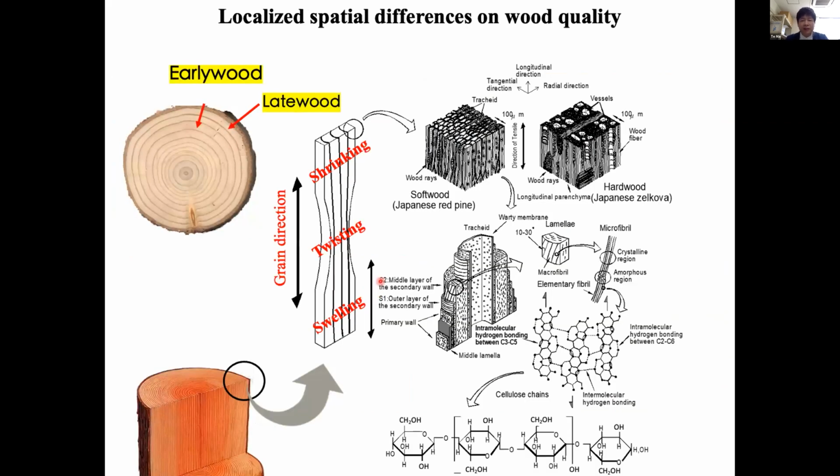However, despite these attractive properties, wood materials are used only to a limited extent in industrial applications compared to steel and brick. Not only because wood material has a complex tissue that suffers from poor dimensional qualities, including swelling, shrinking, and twisting, but also because wood material is hygroscopic. That means it exchanges water with its surrounding environment, resulting in changes of mechanical properties.